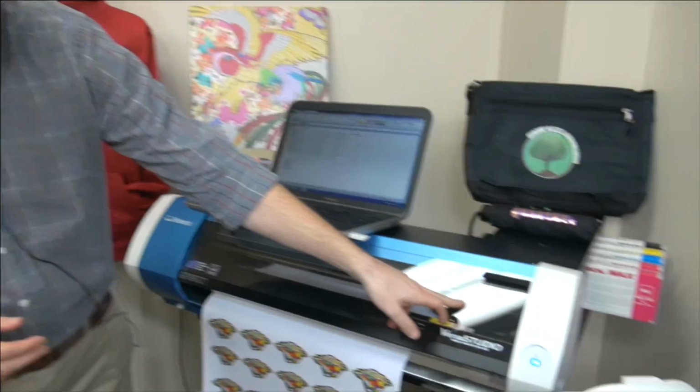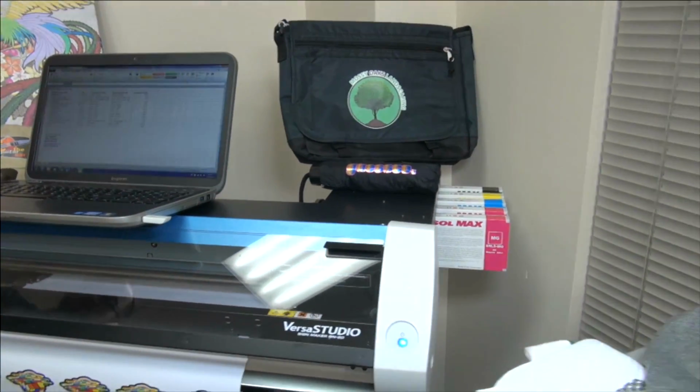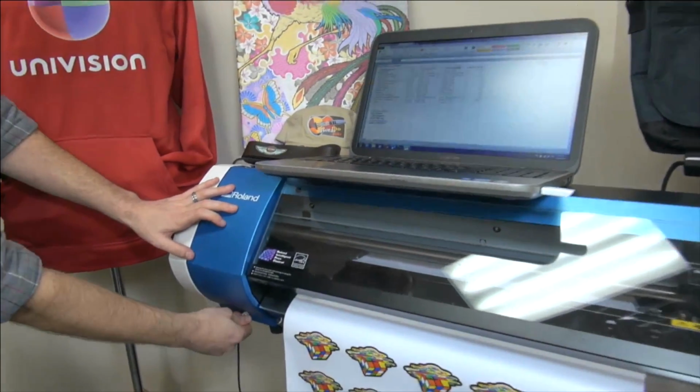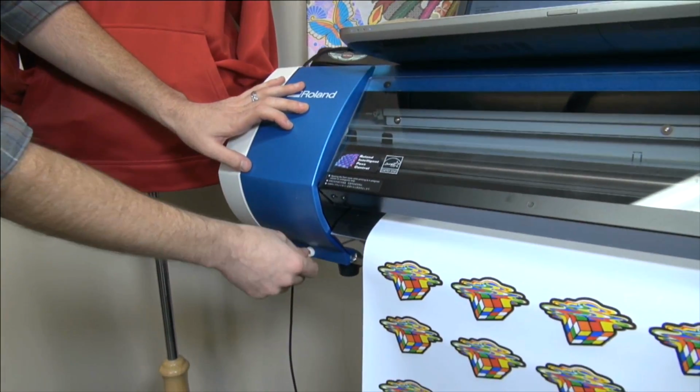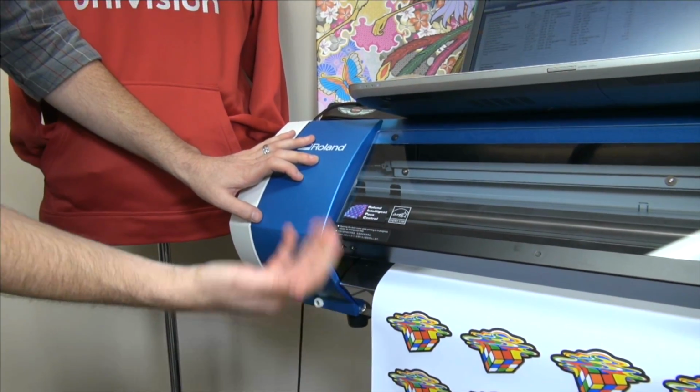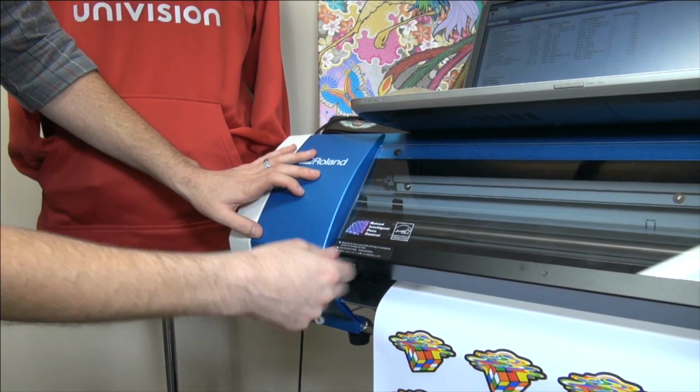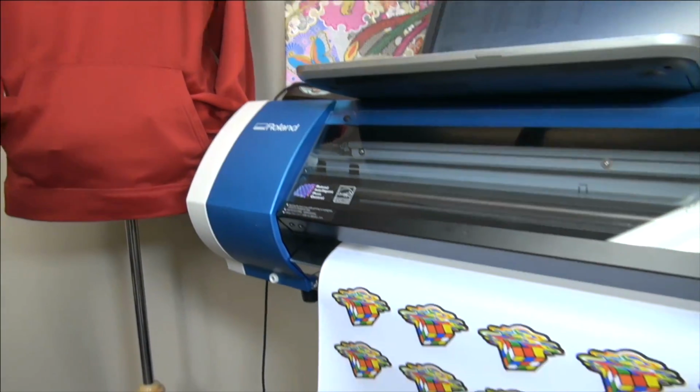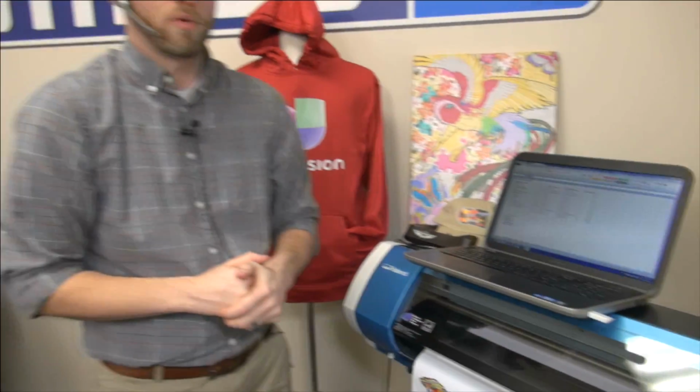The additional maintenance that you would have to do on the machine is cleaning around the print head. We recommend you do that once every 2 or 3 weeks, and it takes about 10 minutes. All that happens is the print head, which is housed here, moves itself over to this bay. You undo this thumb screw, and you take a solvent and a swab that is provided with the machine and clean around the print head and lock it back up. So again, about 10 minutes every 2 to 3 weeks, your running maintenance cost is dollars per month, not hundreds. Hope that answers the question.